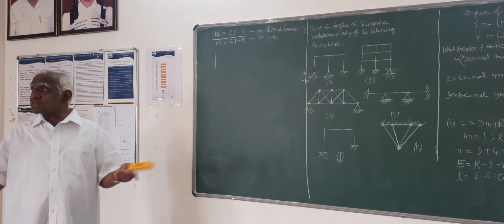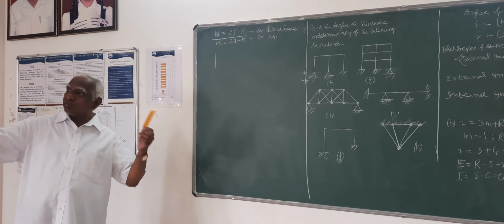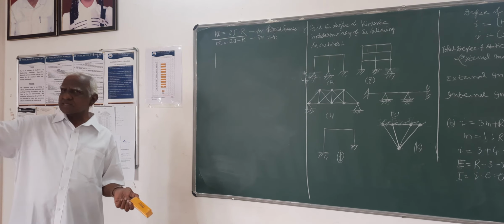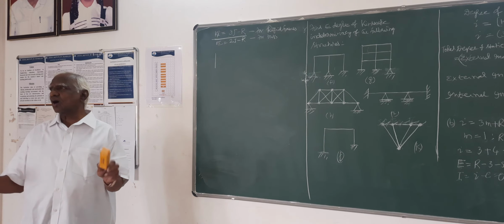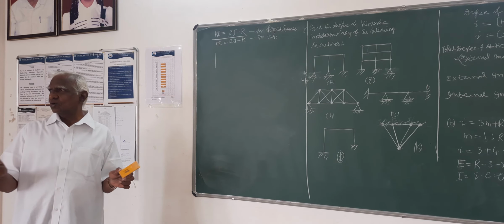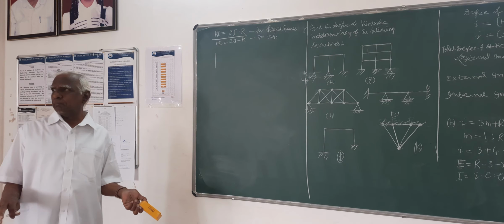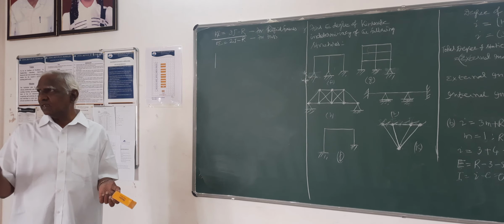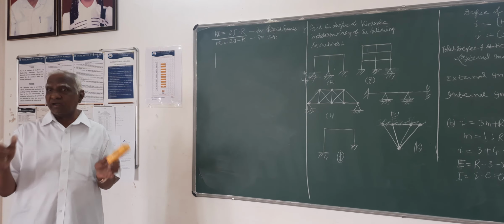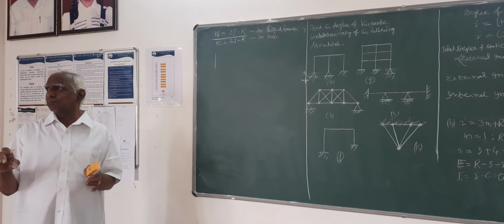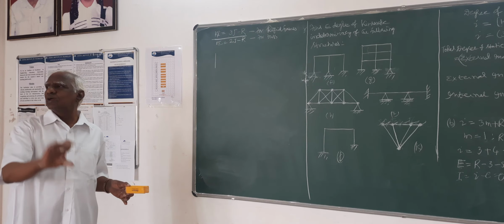There will be three types of motion because movement can occur in any direction. But for analysis purposes, movement in any direction is resolved into three orthogonal directions. In planar structures we get 3, whereas in general space structures we have 6 degrees of freedom: three translations along three axes and three rotations.